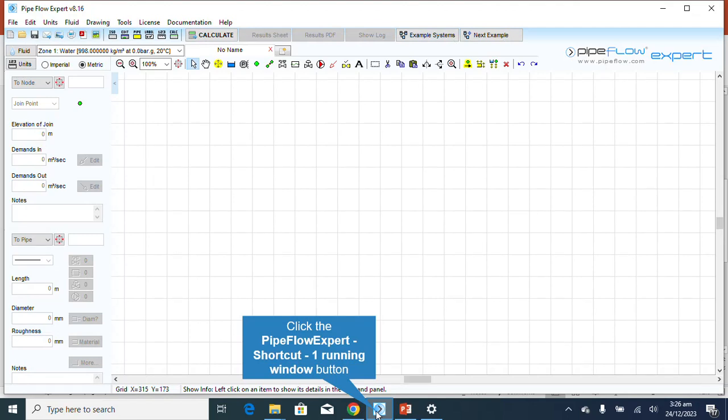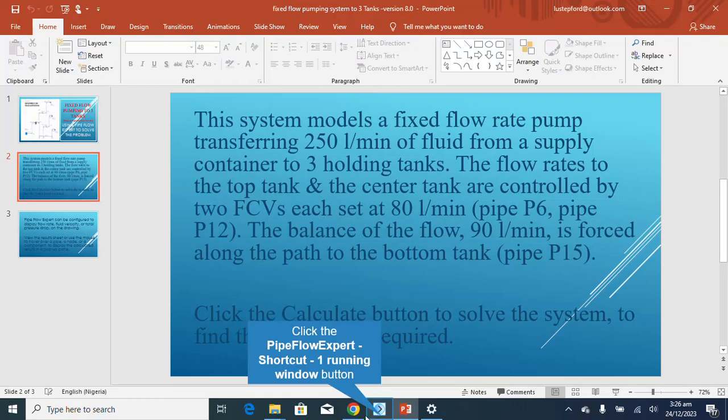You select the pump based on the one that is closest, or if not, the one with the best efficiency, or closer to the best efficiency point on that pump performance curve.